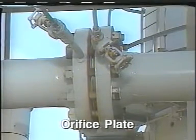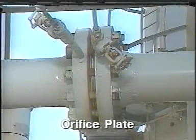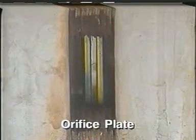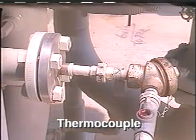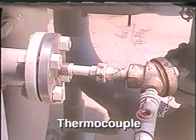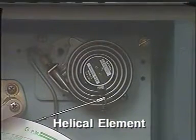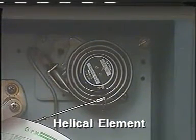These instruments are usually called primary elements or sensors. The devices in this group that are installed directly in process flow lines and process vessels are usually referred to as primary elements. This orifice plate is a primary element for flow measurement. A thermocouple is another type of primary element. It's used in making temperature measurements. This helical-shaped Bourdon tube, used in making pressure measurements, is connected to a process flow line by the metal tubing at the bottom of the element.